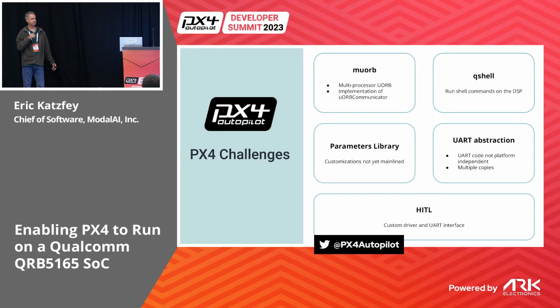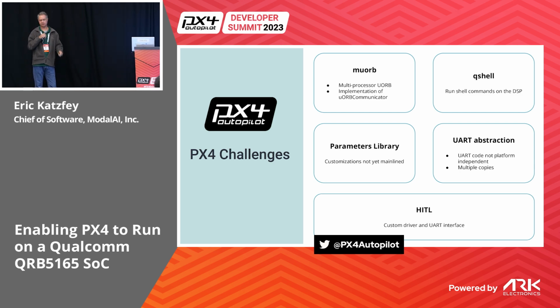This is what abstracts that Qualcomm proprietary code and allows us to, first of all, initialize and send that shared object down into the DSP and get that linked in and set up, and then to start sending advertisements, publish, subscribe, all the standard UORB messages back and forth. That's a very core thing we had to get up and running pretty quickly in order for PX4 to be able to do anything.